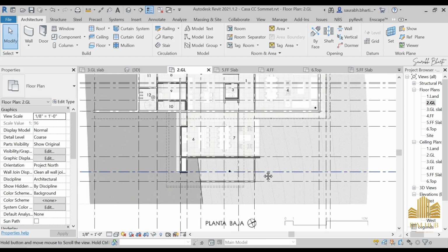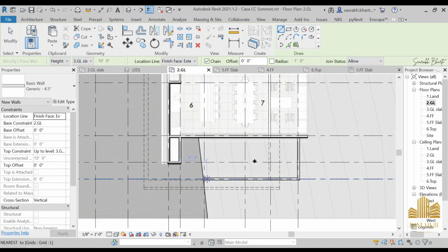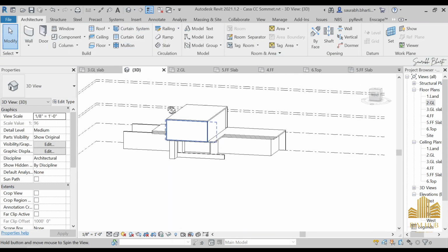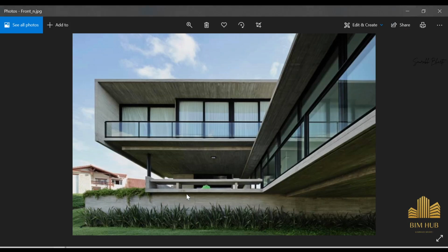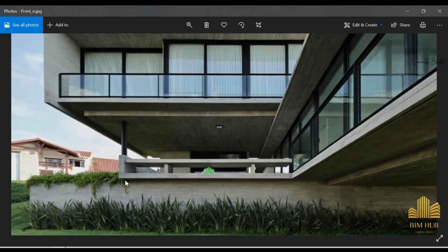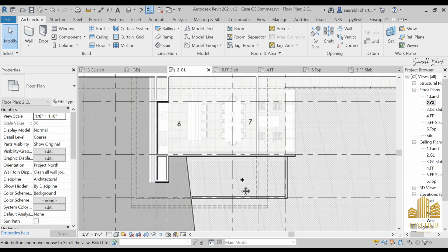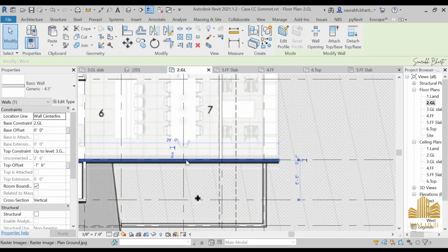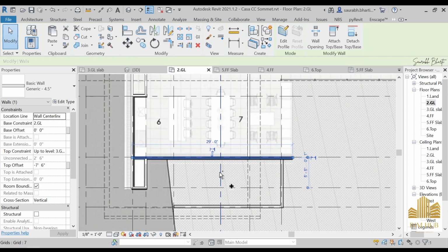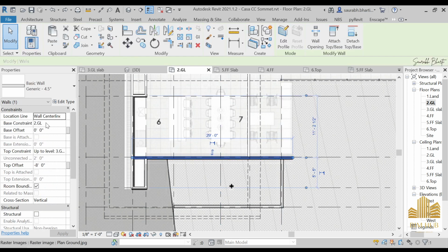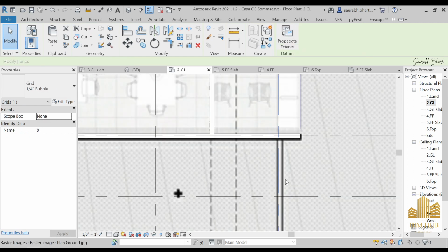Again go to the ground level, select WA, and I think this is a boundary. Okay, that has covered the inner wall, and this is the outer boundary that matches with this place. Let me check. Ground level offset 0. Okay, select.